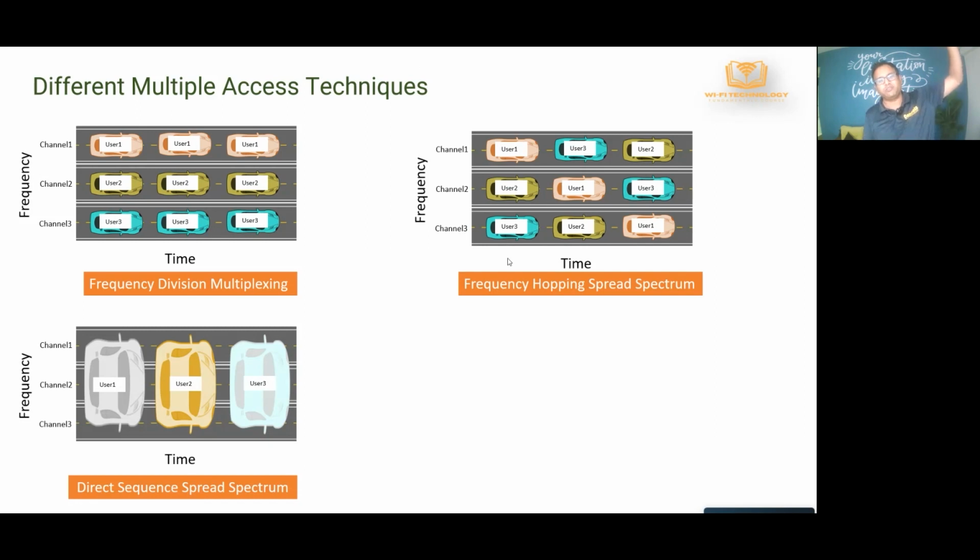So if you have 20 megahertz of bandwidth, I'm going to take the information and spread it across that. I don't need all that bandwidth, but I am actually going to spread that information across the entire bandwidth and transmit information. So that improves the reliability of the communication. It decreases your throughput and spectral efficiency quite a bit because you're not using all the frequencies efficiently for multiple access, but it increases your reliability because you're spreading the information across a wider bandwidth.